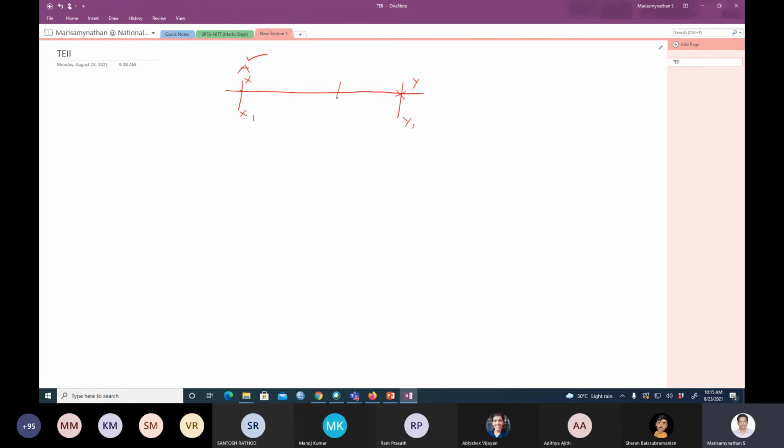So this might be taken at this particular point. From here to here he is taking the decision. Once he has taken the decision, he is applying the brake from here to here, and he stops the vehicle, and this distance is considered as the stopping sight distance, SSD.